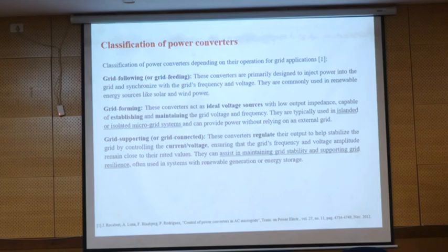So what is happening then? You should buy storage devices to make sure that what you promised is completely met, because based on what you promised, the distribution company also promised to the load side. So for this type of system, we normally use the grid following converter, because we are committed to provide the power to the grid. And if some problem is happening in the grid, we don't care for that one. We are not responsible for that one.